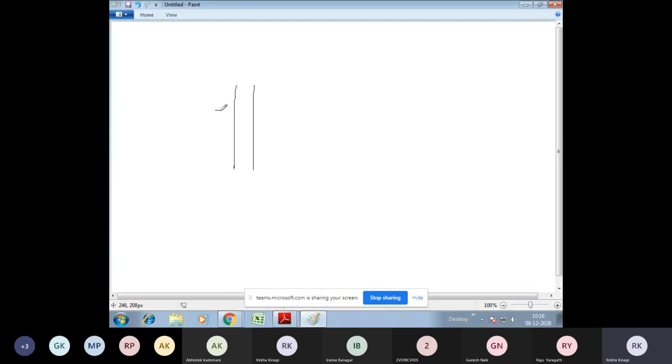But if I take the cross section, a horizontal look, say it is a rectangular column having a rectangular cross section, then these are the lateral dimensions, length and breadth along the cross section, and this is the total height of the column. So the total height we can consider minimum 3 times more than the least lateral dimension.